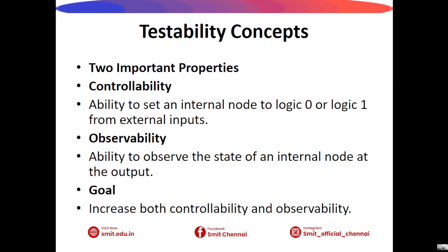Testability concepts. Two key concepts in DFT are controllability and observability. Controllability refers to how easily we can force an internal node to a desired logic value using external inputs. Observability refers to how easily we can observe the logic value of an internal node through circuit outputs. A circuit with high controllability and observability is easier to test and diagnose.